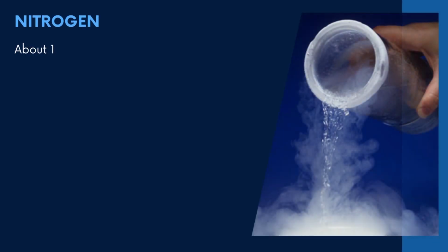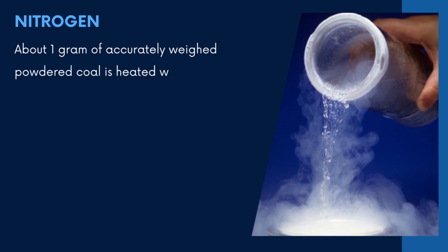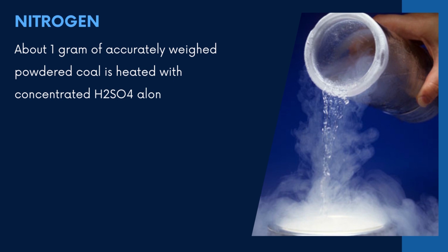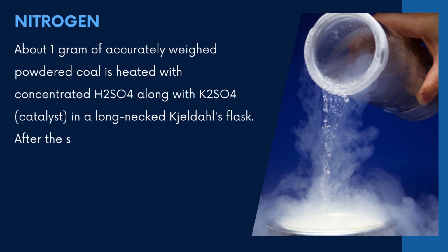Now let us discuss nitrogen. About 1 gram of accurately weighed powdered coal is heated with concentrated H2SO4 along with K2SO4 catalyst in a long necked Kjeldahl flask.